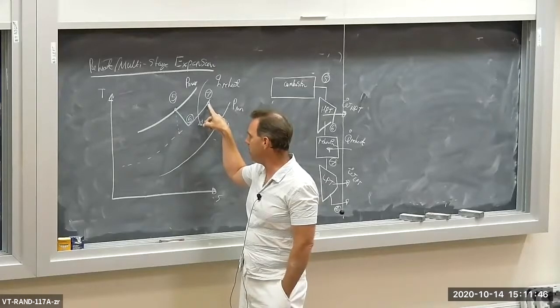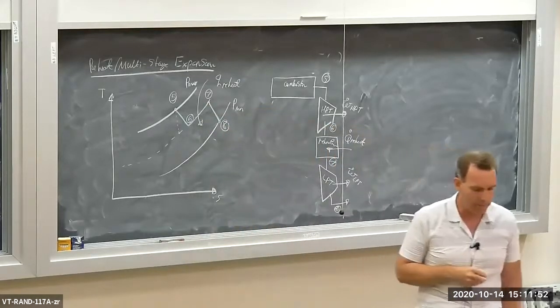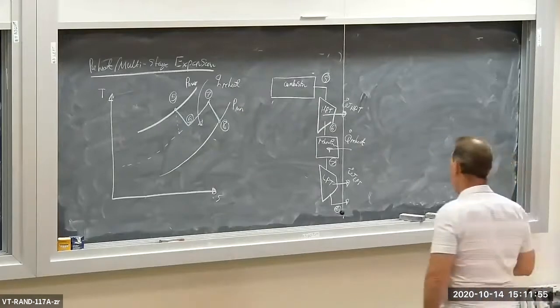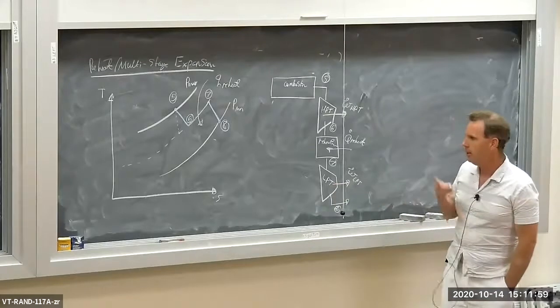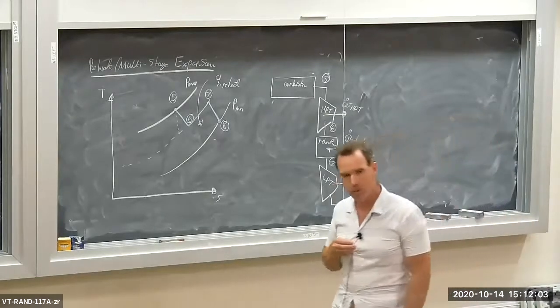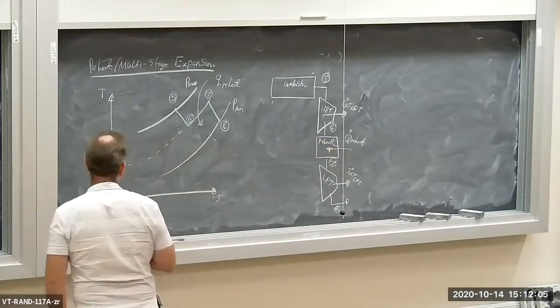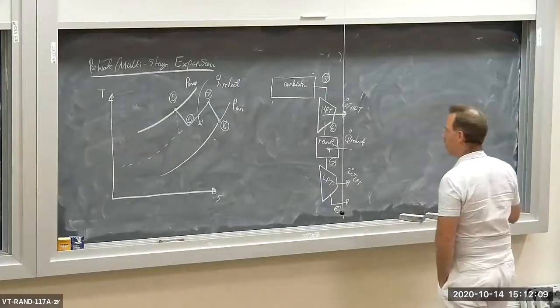Heat up the air, heat up the exhaust, the products of combustion. Then expand, finish the expansion process in a second turbine called the low pressure turbine, LPT. This produces more work, more specific work, and results in more power produced by the gas turbine.